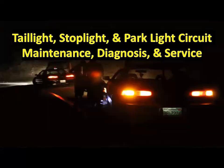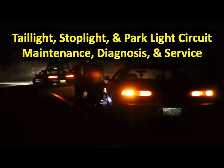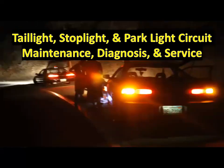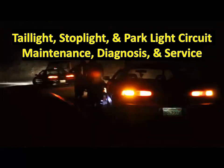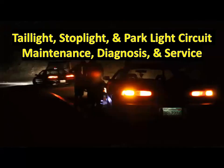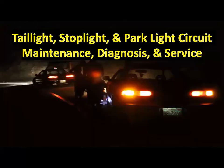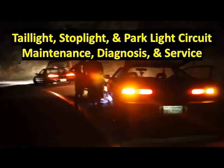Tail light, stop light, and park light circuit maintenance, diagnosis, and service. The maintenance on any light circuit is basically the same. This maintenance includes regular inspections to determine if all the lights are working properly. Light circuit inspection should also include checking the wiring harness for frayed insulation, broken harness retainers, and improper contact between the harness and other components.